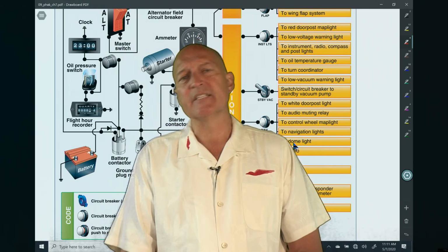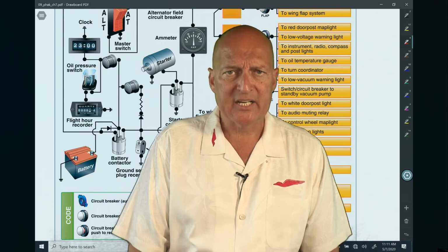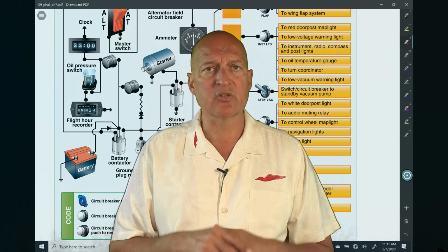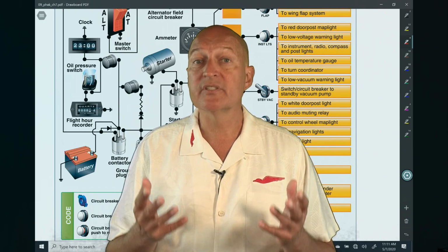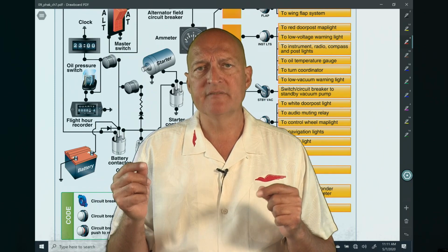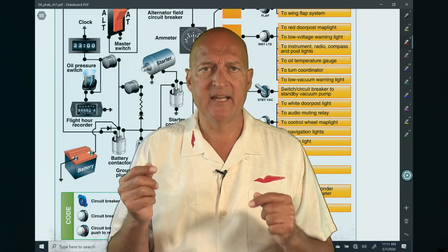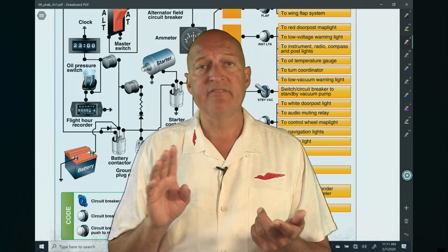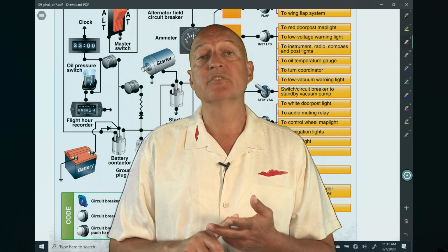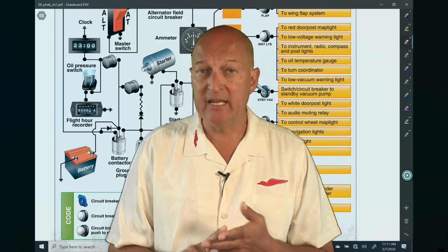A couple of things. You have electricity, as you might imagine. Remember, electrons. So you're going to be bouncing some electrons. The more modern systems are going to use more electricity. You've got a couple of different types of systems that you have inside an airplane. You can have either a 12-volt system or a 24-volt system. Those systems are actually 14 and 28-volt systems.